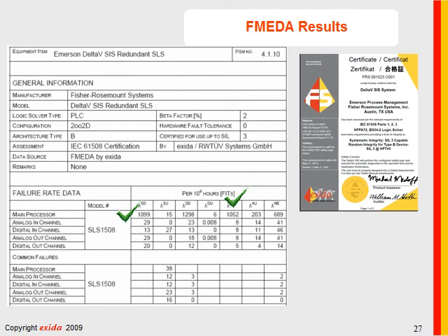FMEDA results, however, do not include maintenance-induced and other site-specific failure attributes. They do not include systematic failures, which shouldn't be included in a probabilistic analysis anyway, but should absolutely be tracked and corrected. And lastly, FMEDA results do not include wear-out failures merged in with the useful life random failures, but a separate parameter for useful life.